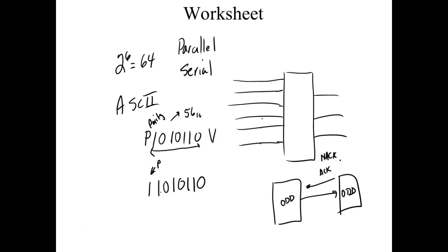That makes sense? So now we had a method where we could transmit data, and this was about 95% accurate. So every once in a while your printer would print a strange character, because the problem with parity is it would detect a single bit change, but if two of the bits in the transmitted data changed, it would still say it was okay.